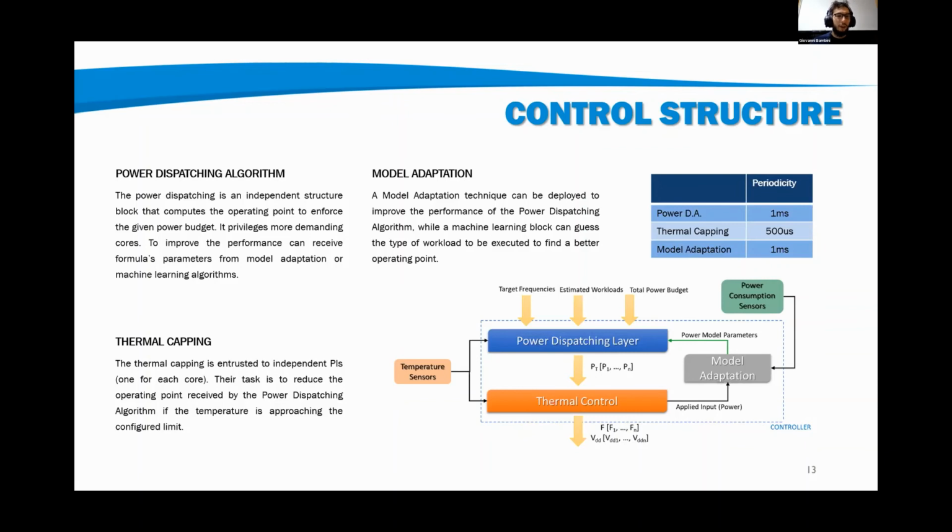The power dispatching layer has an algorithm that gives power based on the thermal room available for each component in order to prioritize the hottest components and the hottest cores that are supposed to be computing the more demanding tasks. Instead, the colder cores and components generally are executing some memory-bound computation. And then we can see later the results that we achieved.